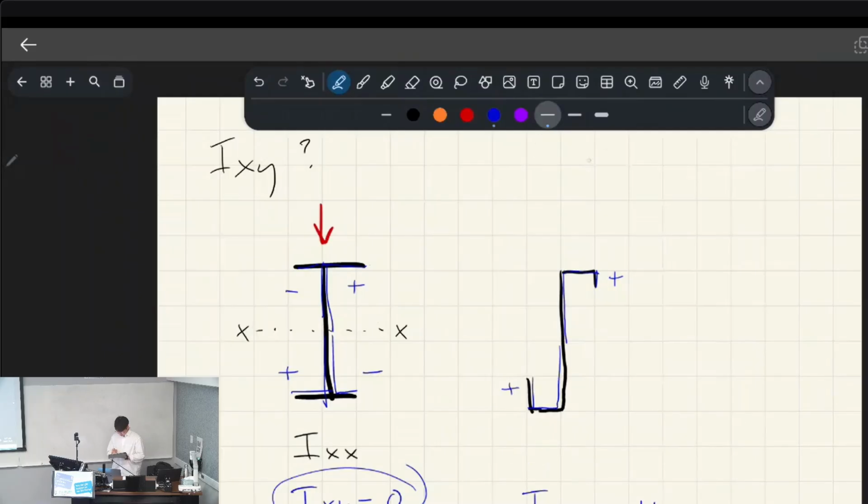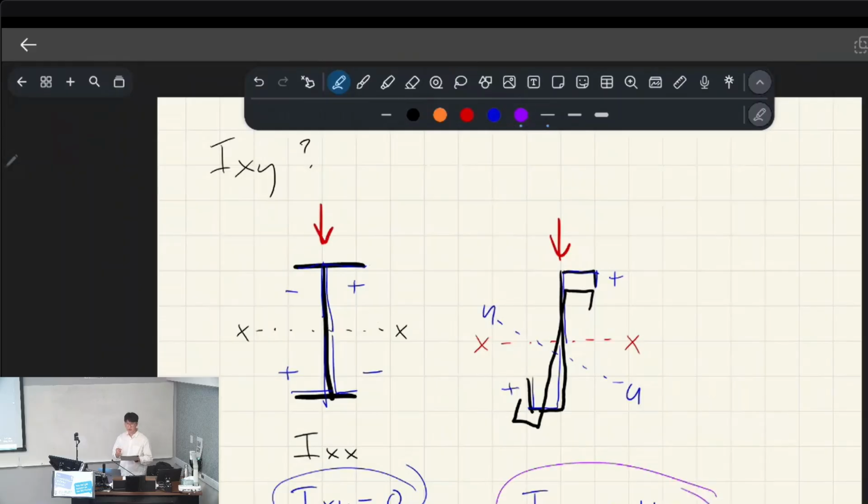So, with that said, if you apply a force onto it like this, even though technically the axis that it's going to be bending about is the one perpendicular to that force, the x-axis, you're going to see that as it deforms and bends, it's actually going to want to do this. So it's going down, but it's also warping almost to the side. And that's because it actually wants to bend about its strongest, or stiffest, axis, which let's call the UU axis. That's because we have a non-zero product of inertia.